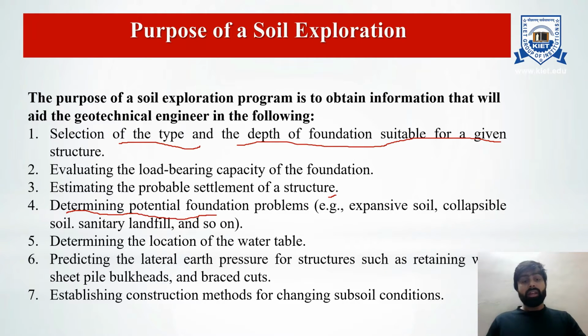And the fifth one, determining the location of the water table. Sixth one, predicting the lateral earth pressure for structures such as retaining walls, sheet pile walls, sheet pile bulkheads, and braced cuts. And the seventh one, establishing construction methods for changing subsoil conditions. These are the purposes of subsurface or soil exploration.